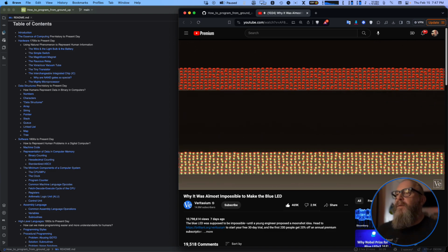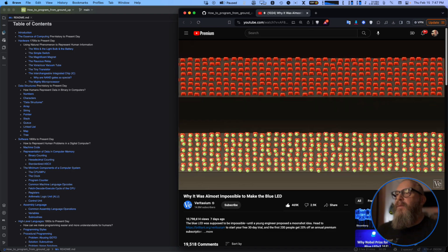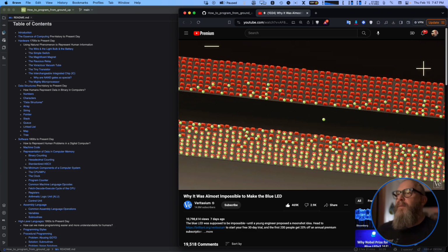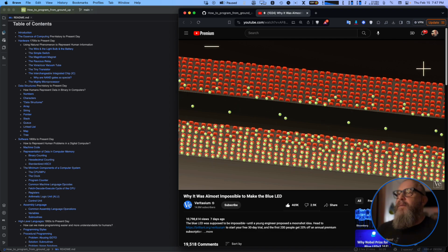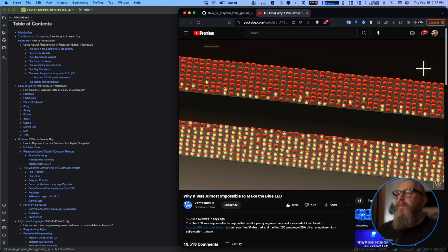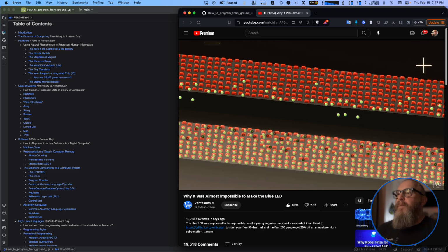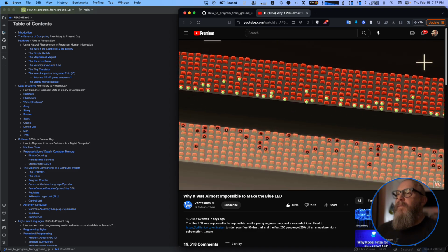Which brings us to semiconductors. Semiconductors are similar to insulators, except the band gap is much smaller. This means at room temperature, a few electrons will have sufficient energy to jump into the conduction band, and now they can easily access nearby empty seats and conduct current. Not only that, the empty seats they left behind in the valence band can also move. Well, really, it's the nearby electrons jumping into those empty seats, but if you look from afar, it's as though the empty seat or hole is moving, like a positive charge, in the opposite direction to the electrons in the conduction band.